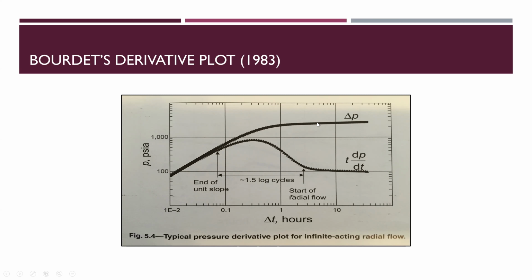This is why I'm reminding you, please take care when you are planning a test design. Try to think about for how long this wellbore storage will last, and what you need exactly from the reservoir. Are you targeting only the reservoir, or are you targeting the boundaries themselves?